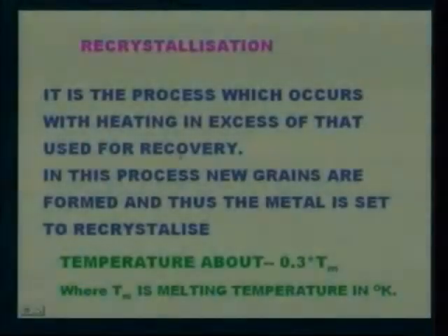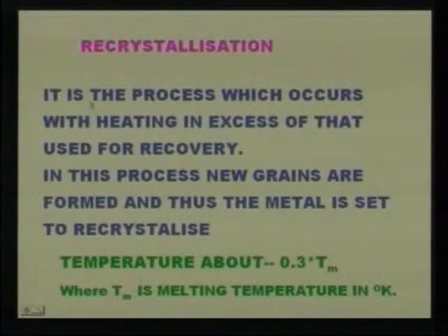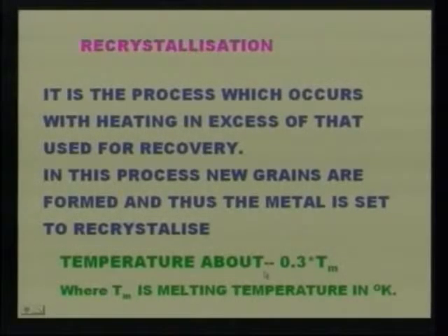Now, let us know about recrystallization. Recrystallization is the process which occurs with heating in excess of that used for recovery. In this process, new grains are formed and thus the metal is said to recrystallize. Here the recrystallization temperature is about 0.3 Tm for pure metal, whereas 0.5 Tm for an alloy, where Tm is the melting point in Kelvin.